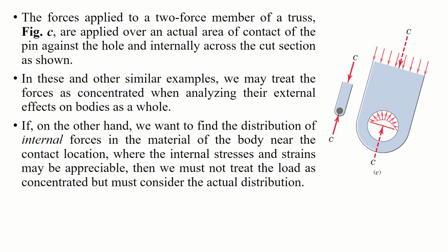Now, in these and other similar examples, we may treat forces as concentrated when analyzing their external effects on a whole body. If, on the other hand, we want to find the distribution of internal forces in the material of the body near the contact location, where the internal stresses and strains may be appreciable, then we must not treat the load as concentrated but must consider the actual distribution. This problem will not be discussed here because it requires knowledge of materials which belongs to more advanced levels.